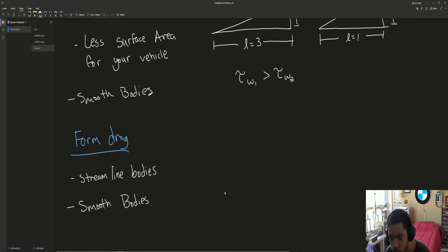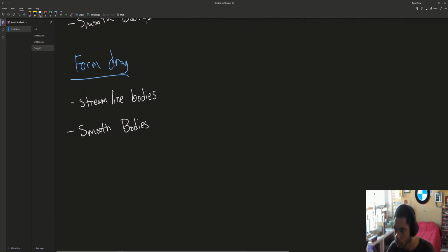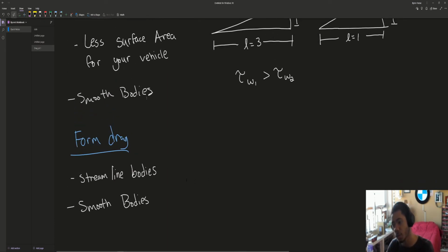Well, microscopically smooth is good. Let's say you have a body that isn't microscopically smooth. This again goes into streamlining. So you have a body that looks like something like this. You just start getting separations just because of the form itself. Viscosity doesn't even need to do anything about it. Curvature won't be enough, and therefore the form drag will come into place.